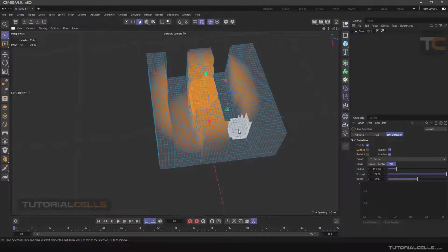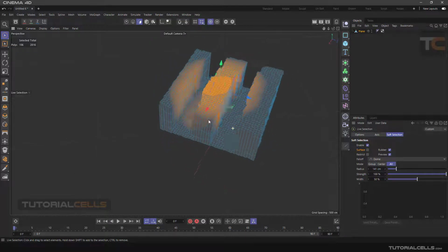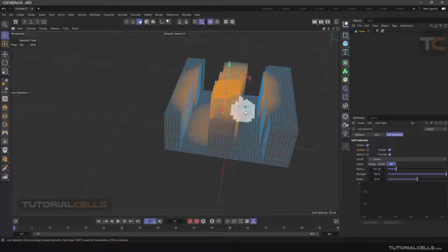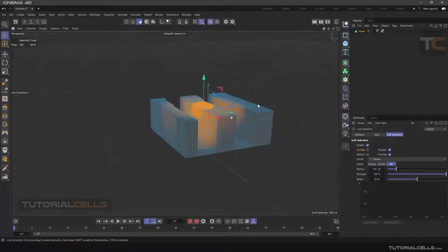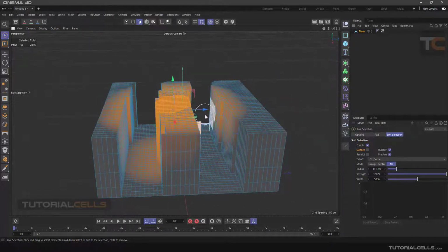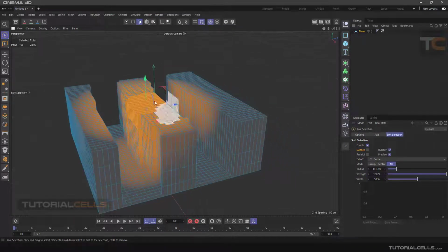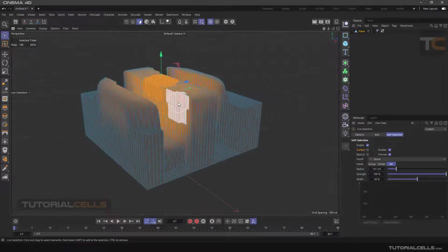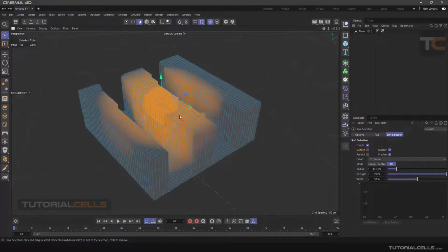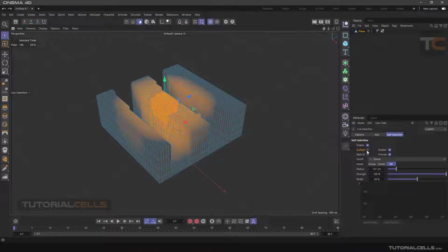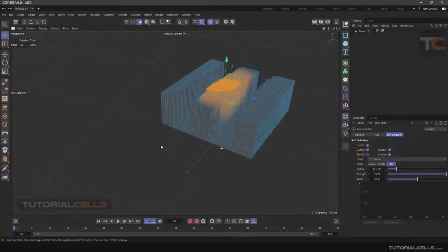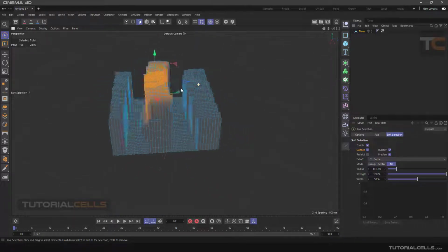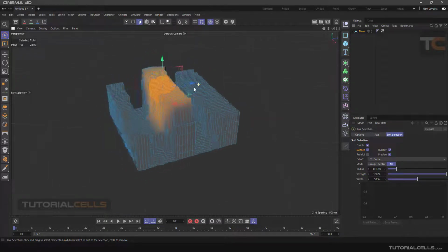As you can see, it seems that the software ignored the height and elevation and applied this tool from above, like a spotlight. If you drag a selected location up, all parts of the object will come up, and we do not want this. Now, if we enable the surface option, everything is fine. And the software understands the height and elevation.